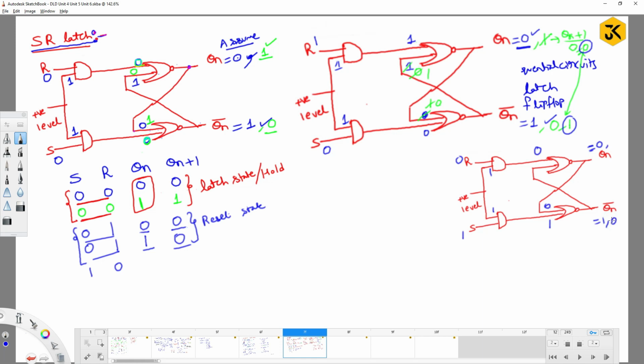Am I right? So which means, is it working accordingly? No, right? So try to observe once again. If I am going to have 0 as input here, 1 0, that same 0 will be getting here and 1 will be there. 1 OR with 0, 1, complement is 0, but actually we should have to get 1. We have to get 1, right? So now try to pass this input to here.